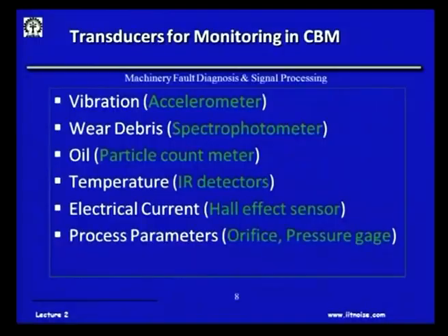In IIT Kharagpur, we have several of them in many departments, wherein all we do is bring in the oil sample. Through a spectrophotometer, we can know its chemical constituents. We can know the composition of these wear debris particles, as to what percentage of iron is present, what percentage of zinc is present, copper is present, etc. And then of course always compare with the chemical composition of the parent material. If zinc is in that component and I have a strong amount of zinc in the wear, I know that parent component has worn out.